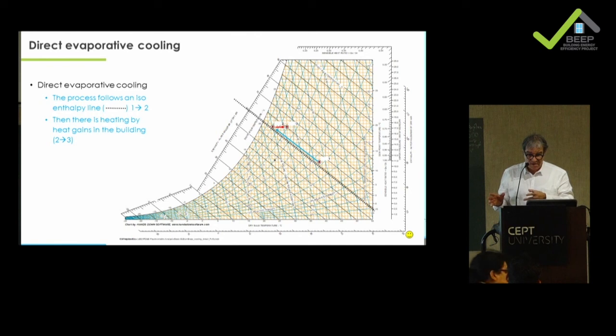But if you make the ratio between a good evap cooling with a cooler and a chiller, there is no comparison. Of course you don't have exactly the same humidity level, but even with two-stage or indirect and two-stage cooling, you can sometimes reach temperatures below the wet bulb. So potentially in many of the hot and dry and composite climates, evap cooling can really be an excellent solution for many situations, especially for residential and even for office.